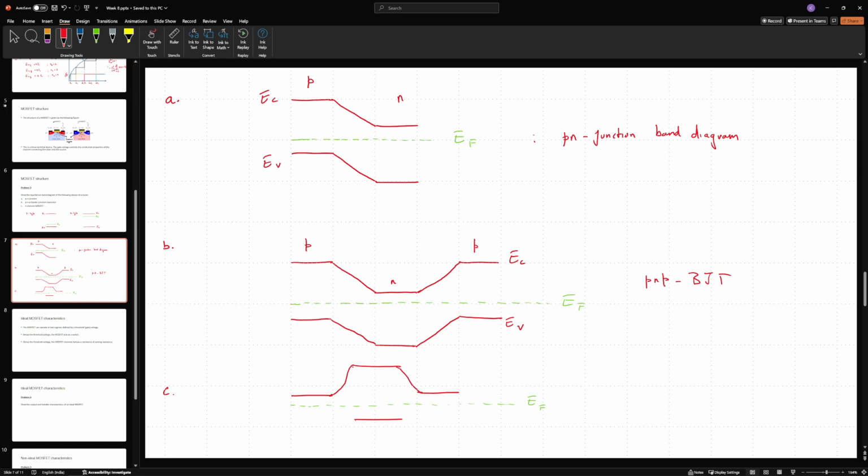Now you can ask, why haven't I made the lines as rigid over here. There is a straightforward reason for that. Essentially, we show this gradient of the conduction band and valence bands only when we have a bipolar junction, only when we are concerned about the depletion layer that forms between the junction, and the depletion layer width is what controls the transfer of carriers.